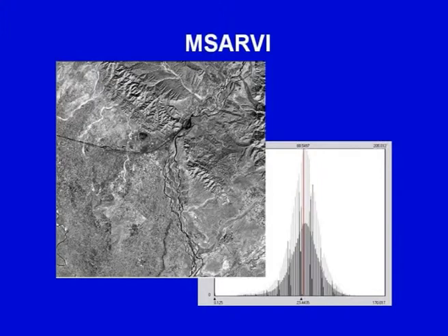What we find here is that the topographic information has again been very explicitly highlighted, and it appears as if we can now identify the micro channels within the mountainous regions, whereas when these streams reach the plains carrying a lot of sediment, they are depicted in white. One of the major rivers flowing through this particular region, all the water carrying channels are seen in black tone, while the abandoned channels or dry channels of the river appear in white or brighter tones.